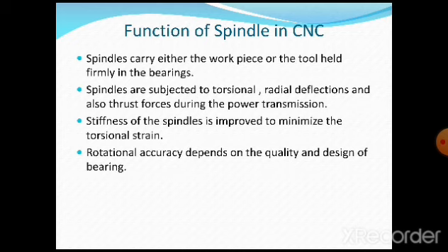That is why the spindles are always subjected to a few important deflections. They are subjected to torsional deflections because of accuracy of rotation and high speed of rotation, radial deflections, and also thrust forces during power transmission.